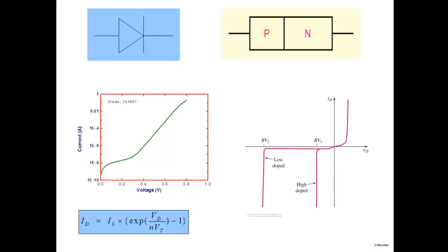You also know that this is the forward direction; if I take the reverse bias direction, the current is small, which we call the reverse leakage current. In the 380 lab, I talked about how the current that you see here is not really the saturation current IS. The current that you see in many PN junction diodes is often much larger than the saturation current. We would like to understand why, and predict the magnitude of this current. Reverse leakage is obviously very important, so we would like to know how to keep the reverse leakage current very low.